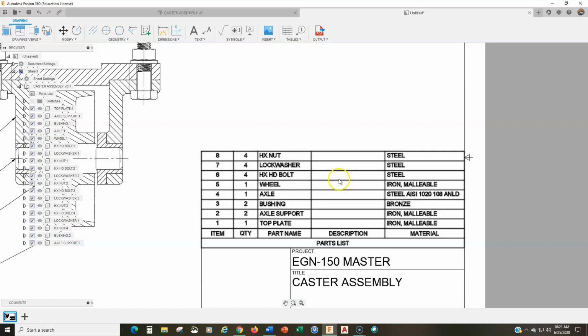That's what you put in the description. Why? Because the bill of material is like your parts list, and so it needs to point the person in the direction of getting that part. So that's why it needs to be a catalog number and vendor, so that they know, okay, I need to go to this company and I need to get this number of part.